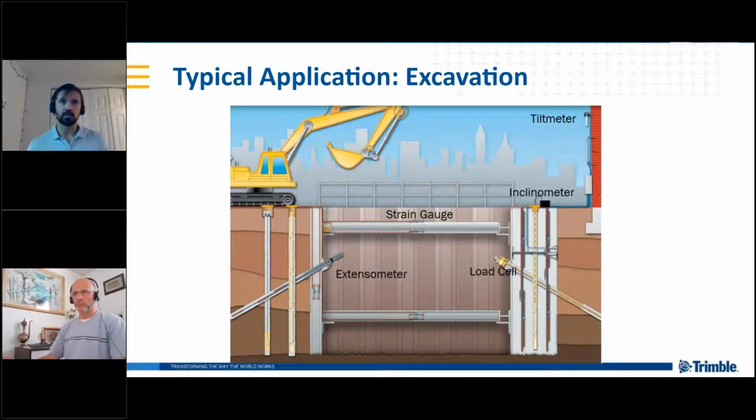Now in excavation, so let's say creating a big pit for building a structure, the foundation of a structure, you have the shoring and different things around the excavation where you're installing various sensors to understand how the load from the surrounding ground and movement, maybe of traffic surrounding it, is affecting that structure, whether that's the load cells measuring the force and the strain, but inclinometers also measuring changes in the structure, whether that's an angle or position, and a variety of other things like strain gauges also checking the stresses on those structures.